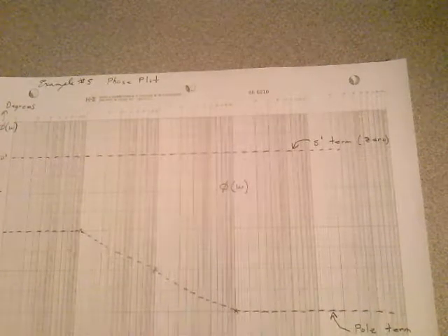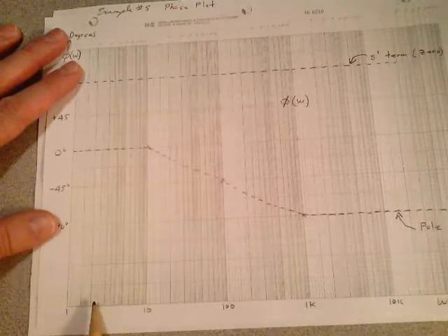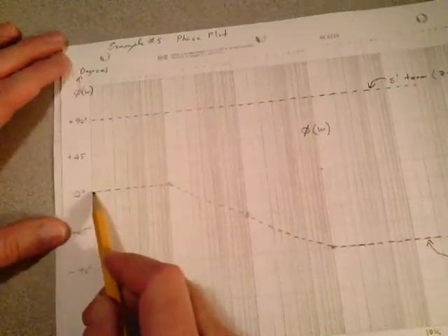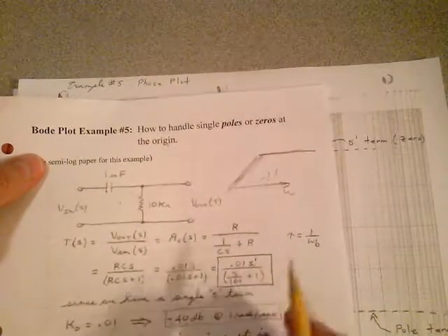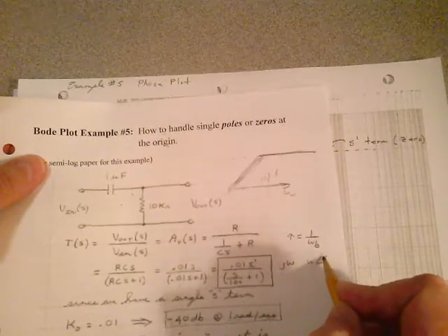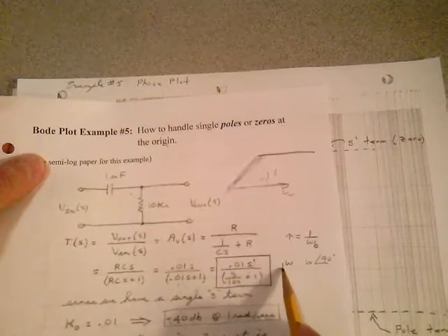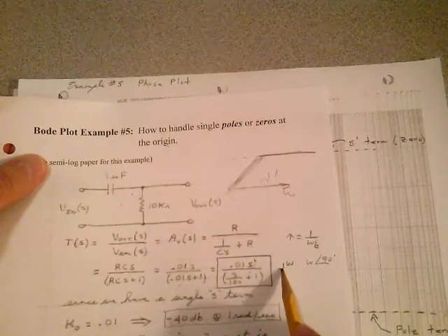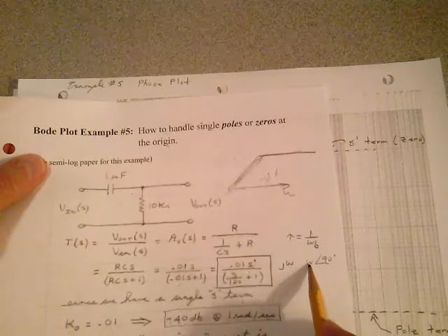So what do we do if we take a look at the phase plot? The phase plot here is on the next page. I laid out my radians frequency at the bottom the same way. I have my 0 degrees here. I put +45, +90, -45, -90. My single S term, what does it do? Well, that S in the numerator is j omega. Think about that, j omega. Well, that's omega at an angle of 90 degrees all the time. The angle's 90 degrees all the time. Omega can change, it's just changing the magnitude. It doesn't affect the angle.